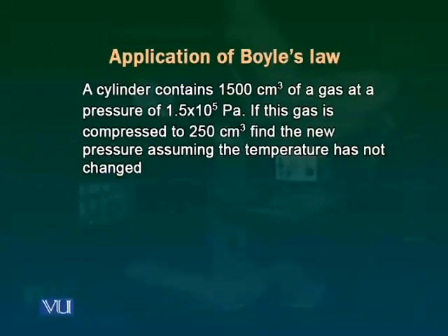Boyle's law basically is very easy to verify. On one side we have a container with water, on the other side we have a tube which is sealed at the top, has a mass of air in it, and as we increase or decrease the height, the pressure, which is equal to rho gh, like we know, increases or decreases, and the volume will change inversely. As you increase the pressure, the volume becomes less. You decrease the pressure, the volume becomes more. This is basically what Boyle's law is.